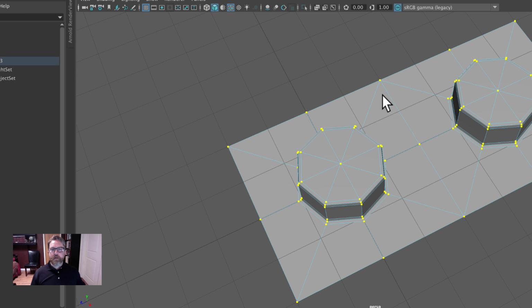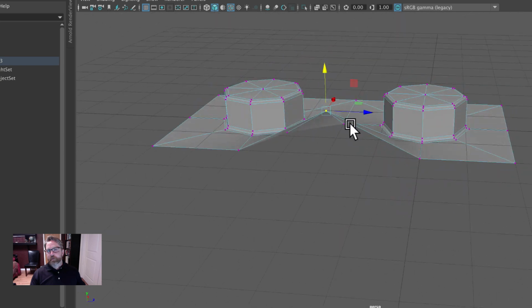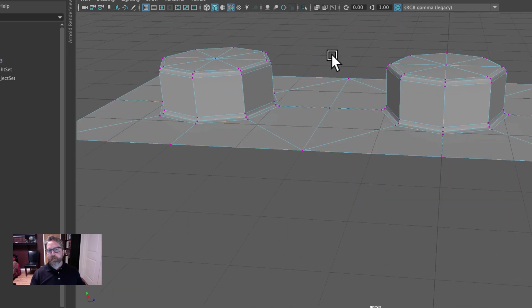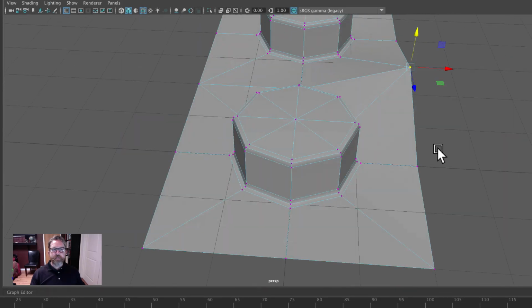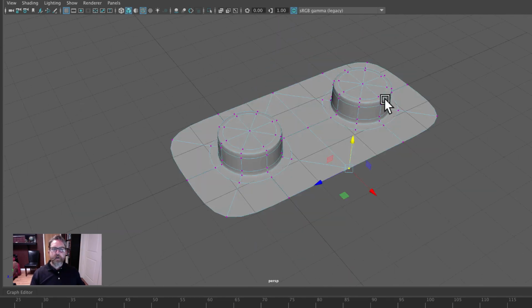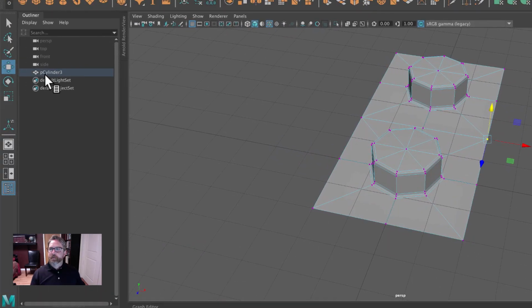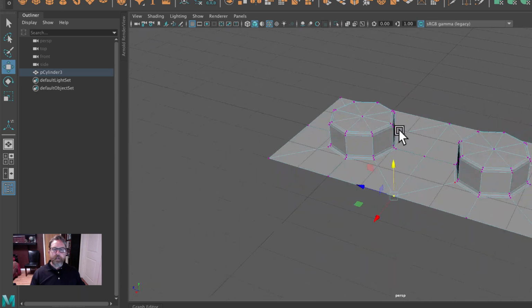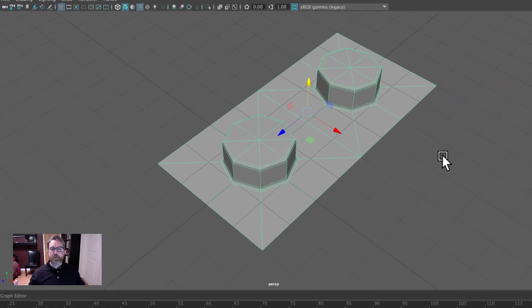And so we'll hit merge, and then we can verify that. We can hit the move tool, and you can see that that has merged. The middle one has merged, and this third set out here of vertices is now singular, it's 1. You can hit the 3 key. We still have a rounded edge out here. We'll solve that when we bevel at the very end. But this singular polycylinder 3, currently named, is a single mesh. And then we can pick up with the same tools and techniques that we used on the first part of this video to complete the process of creating our brick.